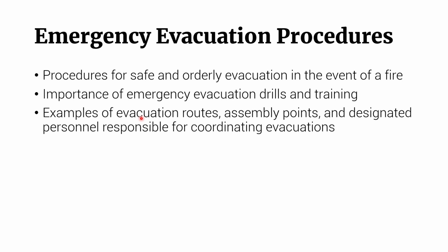First is the fire exit. We know there are markings on it. And our routes must be clear and free from obstruction. Maybe your markings are being covered, so people won't be able to see them. Make sure your markings are free from obstruction and also with multiple exits to facilitate quick and efficient evacuation.